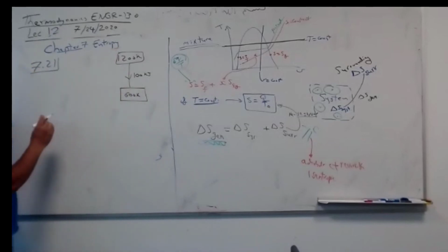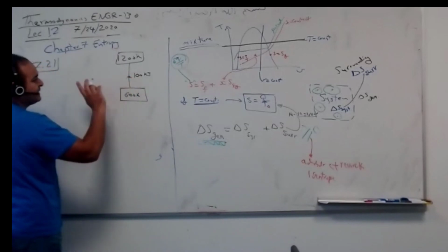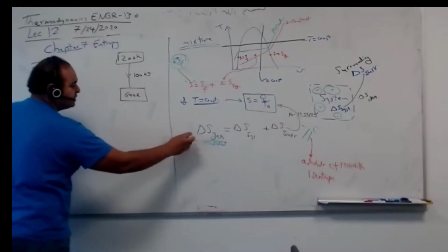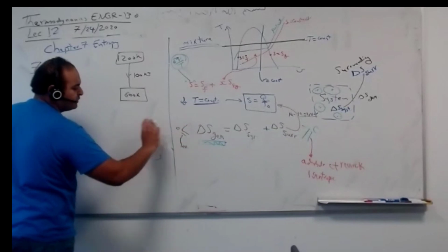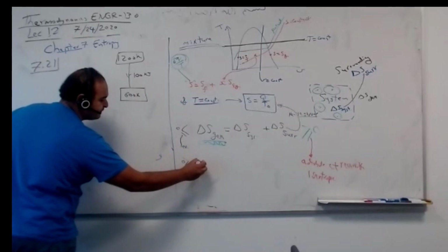That's what we said in the first law of thermodynamics, correct. Even if it's like this, in the first law of thermodynamics, it's correct. But the second law says, no, that's not correct. Let's see that now. So delta S generation should be greater than or equal to 0. It is 0 if it's reversible, greater than 0 in reality, and it's impossible to be negative.